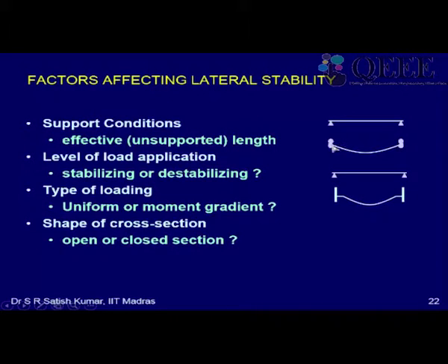Okay. So by putting just two rollers like this, I am saying that deflection at either end is prevented, but rotation in plan is allowed. That's why this beam is able to buckle laterally in this manner. But if I suppose built in this end in plan, that is I put two more rollers, then this beam has to come out essentially in a straight line, and away from the support only it will be able to buckle. So this will become like a fixed end condition in plan.